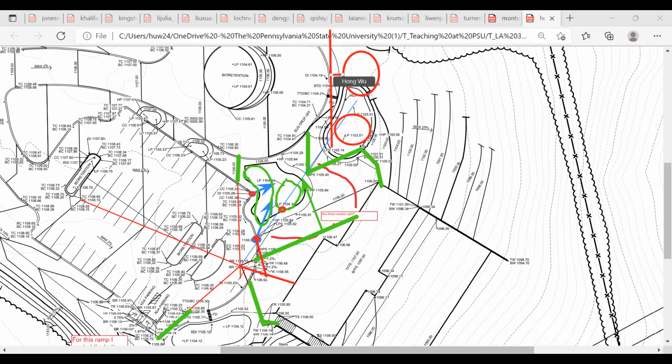And then this one can be smaller because you already have, well, let's see, unless you don't allow water to go in there for this higher portion and have a little wall here and everything just drains along that curb down. But I don't think that's necessary either. I don't think that's a good design either. So I still think separating them, you have room to separate them, and it's probably not a big hassle in terms of grading. So I would recommend doing this.